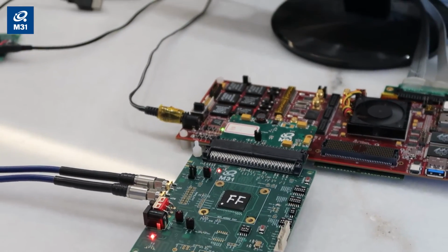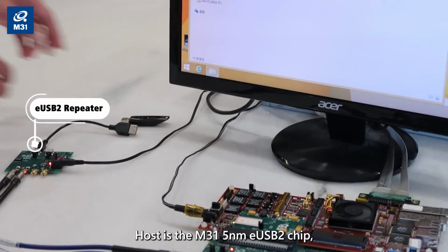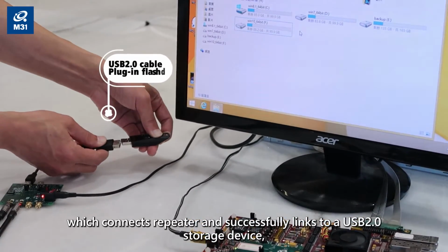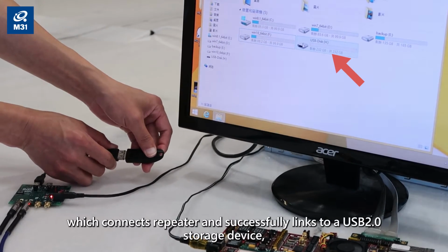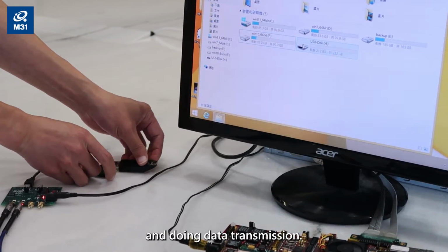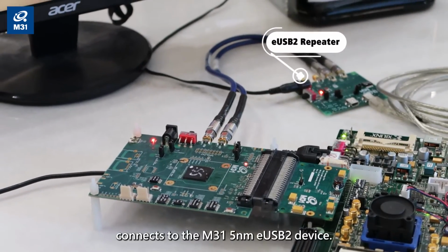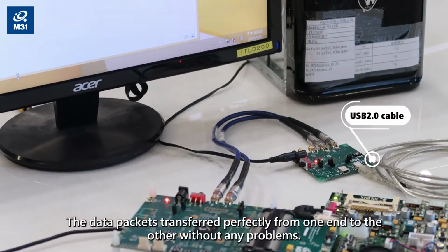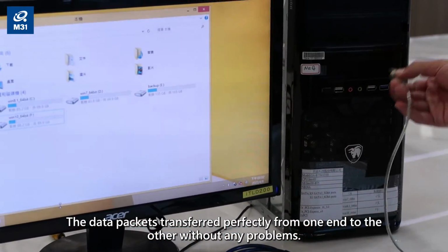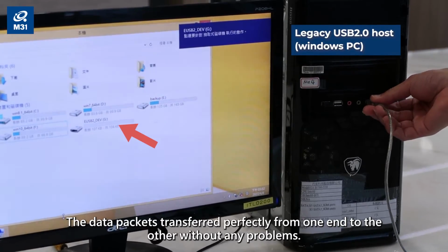Secondly, we show the eUSB2 host connected to a conventional USB 2.0 device via the TI repeater. Host is the M31 5nm eUSB2 chip, which connects to the repeater and successfully links to a USB 2.0 storage device and does data transmission. On the third, we show a USB 2.0 host via repeater chip connecting to the M31 5nm eUSB2 device. The data packet transferred perfectly from one end to the other without any problems.